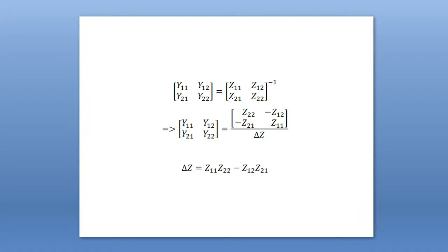In the same way, with input port and output port, you click simulate and you will get the values of h11, h12, h21, h22. Then you consider the relationship between z parameters and h parameter, put in the values of the z parameters and check the theoretical values. Finally, you compare theoretical values and experimental values for the h parameter case also.